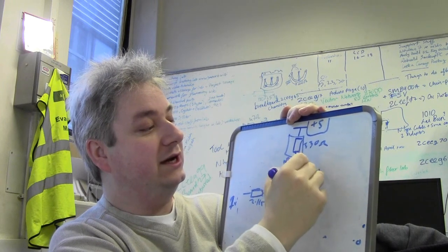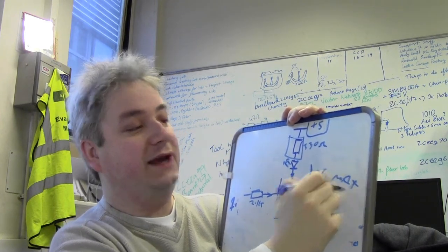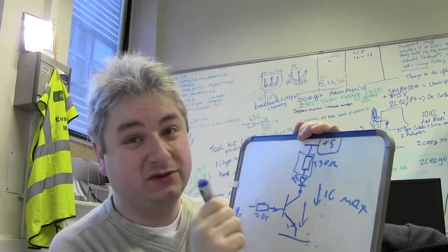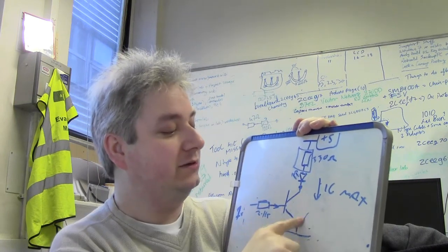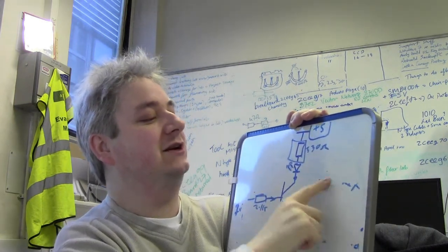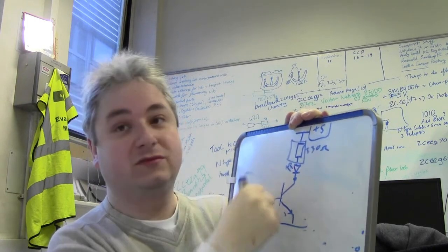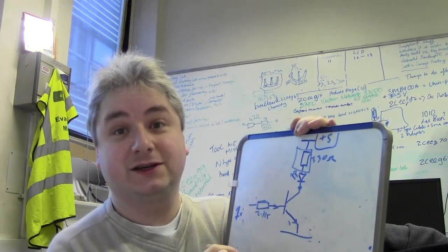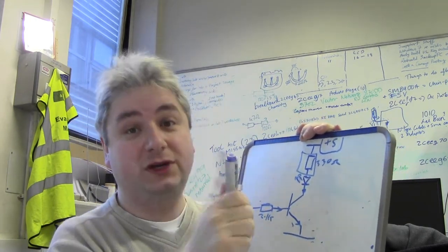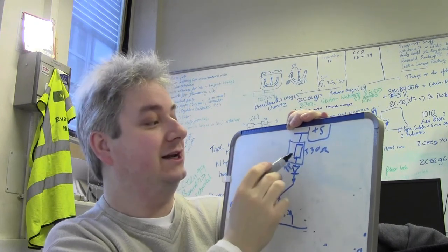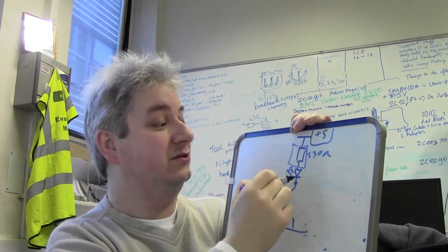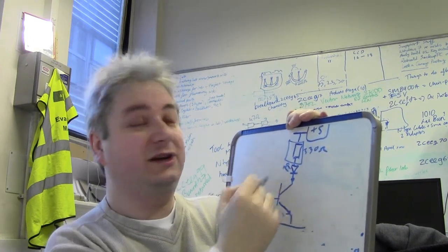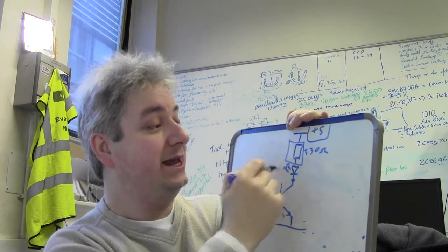Your IC is worked out to be IC max. That's the maximum current draw that could possibly flow through your transistor. That's not the actual current that's been drawn, that's the maximum. That's up to the max. And we're actually limiting that amount of current using this resistor. So we're saying, transistor fully on, maximum current flow. Just use that resistor, just like in the previous example where you got too much power. This is going to limit your current to what you need, and it's also going to drop the excess voltage from your supply across that resistor, so you only have the voltage that you need here.